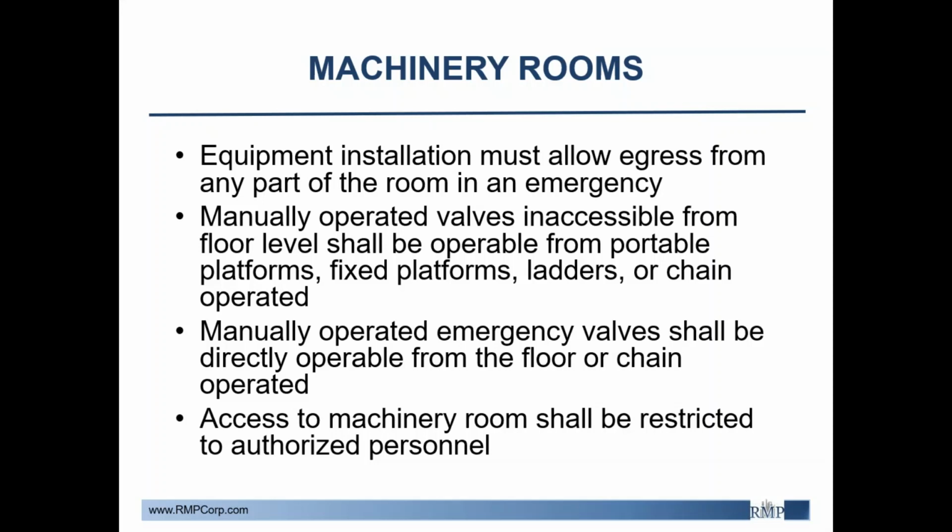Also recommended is some kind of buddy system when working around ammonia. There's a lot of arguments for that reason. If someone becomes overcome with ammonia gas for some reason during a leak, or if they just get hurt, maybe twist an ankle or whatnot, there will be someone else there to go get help.